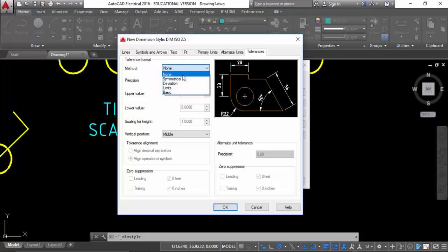exact bolt size and it goes over to site, the people on site are going to be very upset with you because the bolts are not going to fit in. Okay, it won't fit in at all. So the reason why we do that, we will have a 2 mil tolerance in order for the bolts to then fit. Okay, so that's just plain straightforward information that you can take it or leave it.